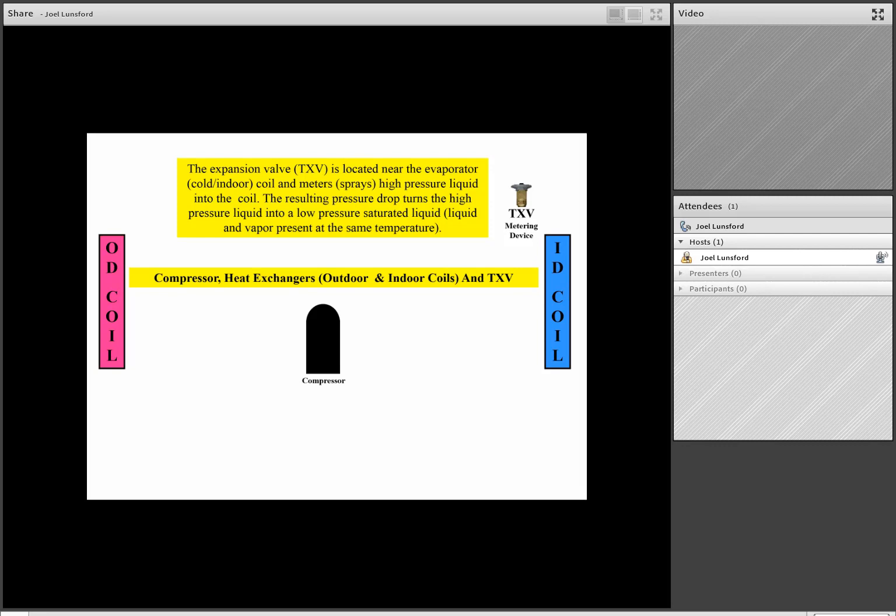Now, team, when we talk about boiling refrigerant in the evaporator coil, let's stress something here. When you think about something boiling, you think about something being hot. But remember, the actual refrigerant, commonly called Freon, in the system is a specialized chemical that's going to boil at 60 below zero for 410A, at 42 degrees below zero for R22, and at about 40 degrees below zero for 407.